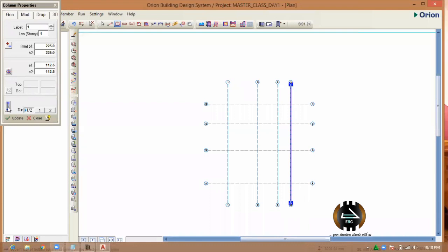So now this is column end conditions. Look at here. This is your column end condition. So if you don't know about column end condition, just leave it. Just leave the column end condition. The software will use its hand and decide. But as an engineer, you can know whether the column is fixed or not. So these are the two edge conditions of your column.